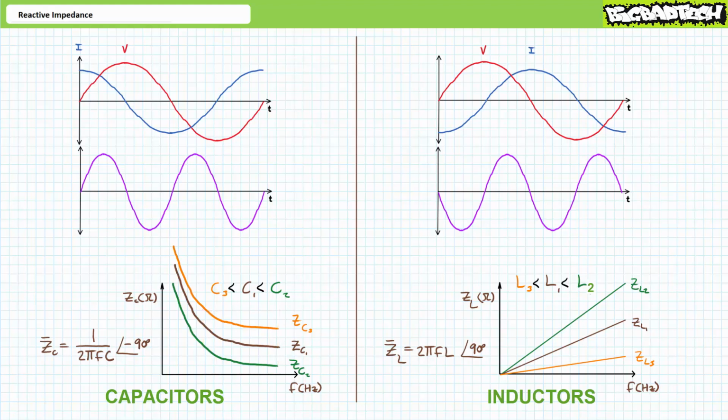This is a reflection of how frequency influences the length of the charge and discharge phase. Slower charges and discharges necessarily result in lesser exchanges of current. More rapid charges and discharges necessarily result in greater exchanges of current. Large capacitors present low impedance and draw high current. Conversely, small capacitors present high impedance and draw low current. This is a reflection of capacitor construction, i.e. a measure of its ability to store charge.